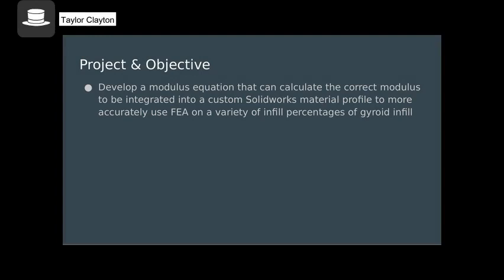So our actual objective is to develop a modulus equation that we can use to create a new substitute modulus that could be used in SolidWorks in a custom material profile to more accurately get results from the FEA based off of what infill percentage you're printing your component at. This is all assuming that you're using the gyroid infill pattern.